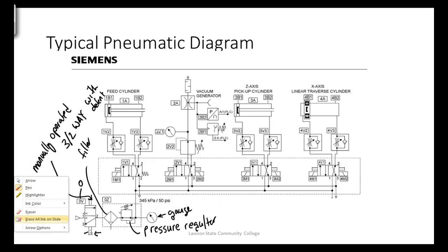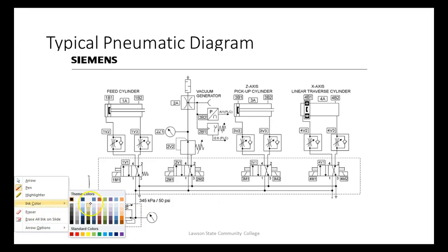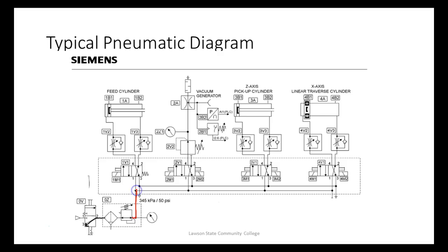So y'all have already played around with that, right? So if we push down on this and shift it down here, we'd take 2 and push it out, and it just vents out. And that's what you hear every time y'all push that e-stop in, right? Or the stop. And then, of course, now we come up, and this is the manifold, that big black box, or that big black cube that's under that. It comes up here and runs down through the manifold. So there would be our pressure, right? So pressure is sitting up here on all these valves.